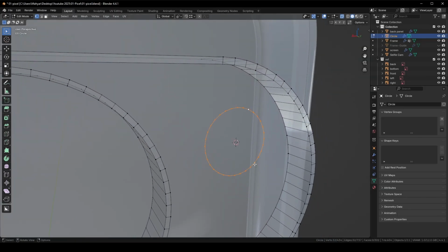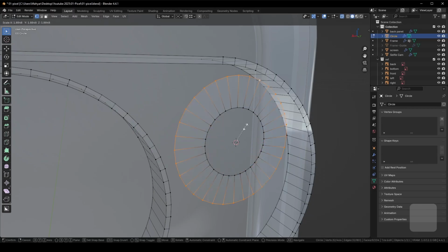Since this is a perfect circle, we can have the edge loop for beveling without needing to create a face and inset. We can simply go to bounding box center, press E to extrude, press F. Since it doesn't have any dimension in Y-axis, we don't need to press Shift Y.